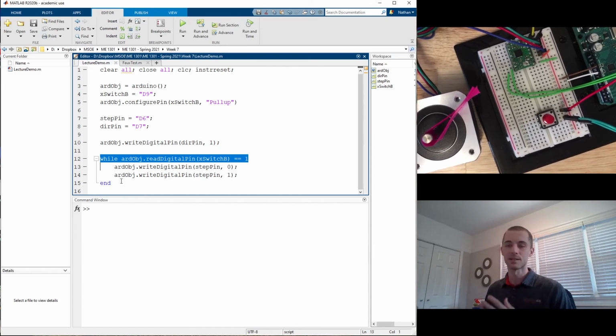And so it's a different switch setup that just inverts the logic for the way that it operates. In the case of the Arduino or the XY table in class, the button is pressed when it's actually 0 and not pressed when the value is 1.